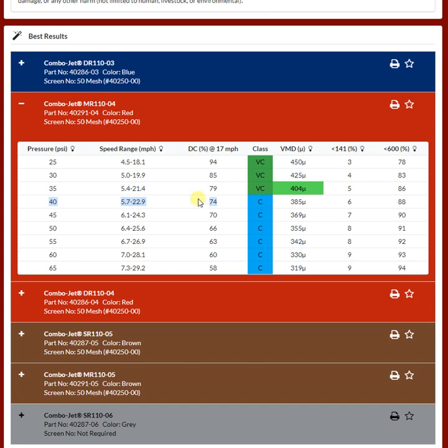So qualifying the nozzle, making sure that, first of all, it is within label requirements. So being at 40 psi, we're in the coarse spray quality, satisfying the requirement. The droplet size is there more so that you have a relative factor of coarser or finer spray if you do choose to use your system a little bit more and change that pressure on the go. So for an example, in typical conditions, we want to try to be around 40 psi to have our droplet size close to that 400 microns.